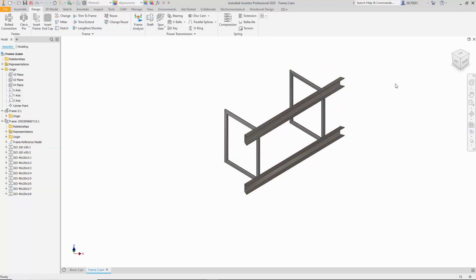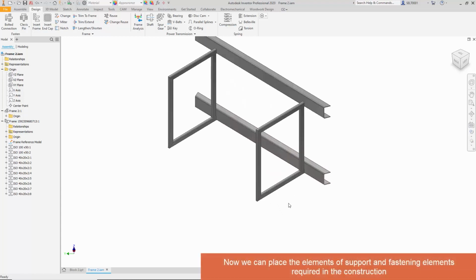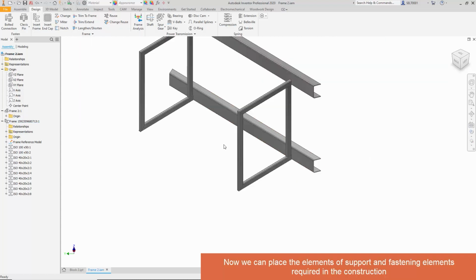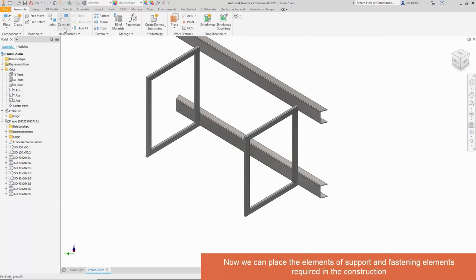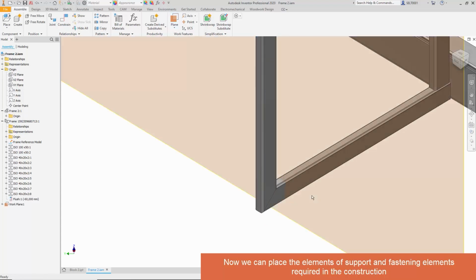After placing them, it will be possible to make reinforcement into one block. We need legs and structural elements that will support our future cabinet, which will fit in the gap between the two metal legs. We use woodwork for Inventor features for this. We choose 60 mm from the edge, then the other leg is also 60 mm from the edge.